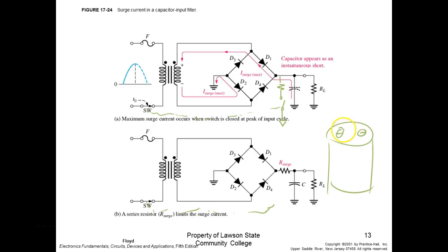And you'll see people take screwdrivers and put them across the capacitor and short it out. That's not good for the capacitor. You've got a $50 capacitor in there, and you're going to limit its life. So a lot of times they'll actually put a big resistor across here to give you something to discharge it. Because if you don't have a load hooked up to that, then you see how long this guy right here takes to discharge those capacitors through its internal circuitry.